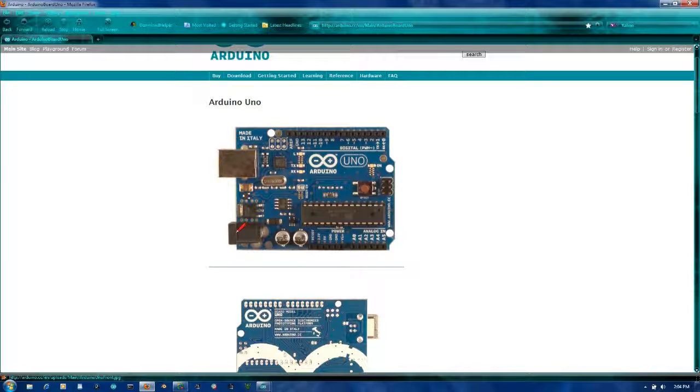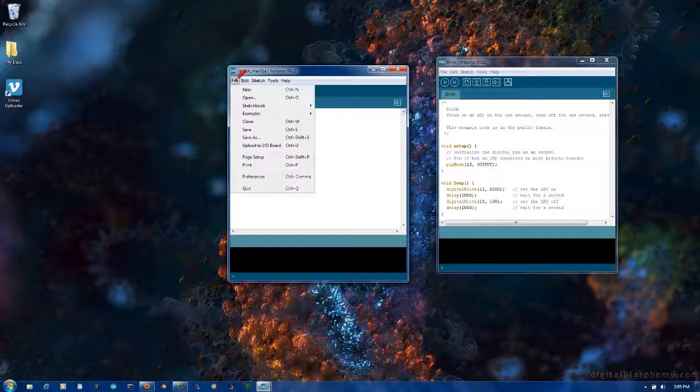I heard you can use up to 12 volts. I actually put in 12 volts in here. I actually fried one of my Arduino chips once, so it was through a car battery, so I think it was actually more than 12 volts, so it wasn't a regulated 12 volts. You generally take a 9-volt power supply, and you can run this perfectly fine off of this without being plugged into the computer. We'll just keep that open in case we need to reference that.